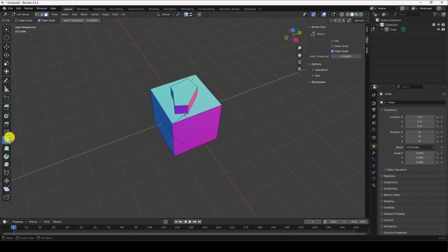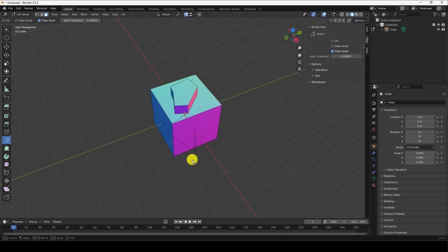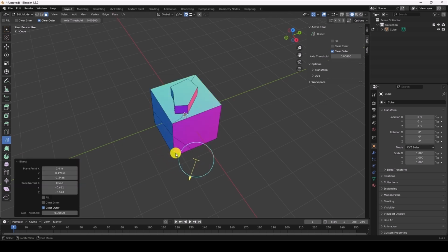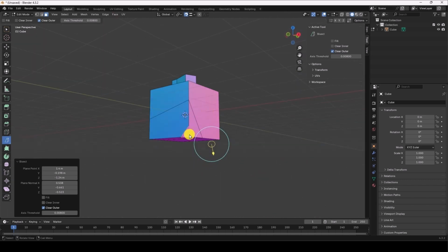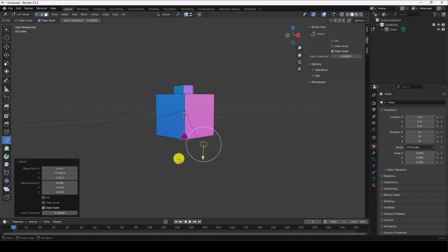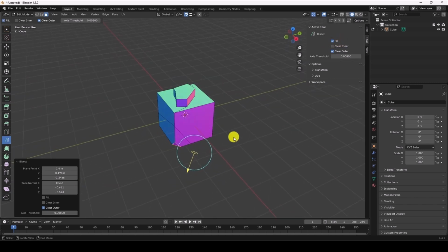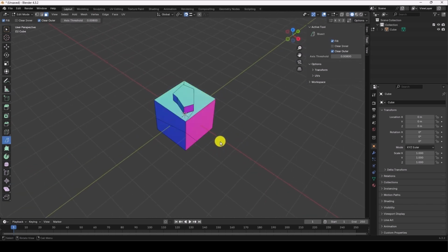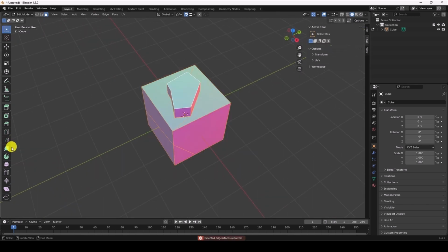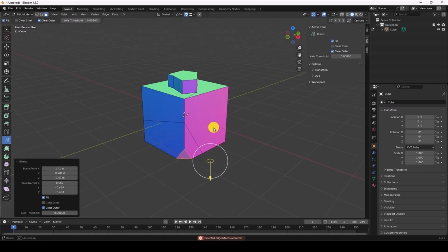So how it works. Now if I select this object, and then bisect this one, let's bisect a small portion of it like this. And then you see that it shows a hole and you can see inside the cube. But if you tick the fill option in and Control Z to come to original shape, and then select this object, select bisect. And now you click and cut a small portion of it. Then you see it is filled.